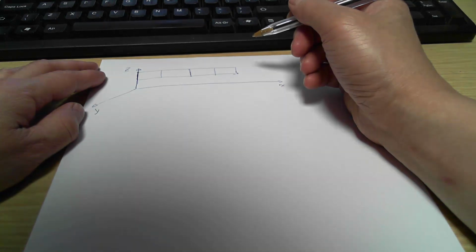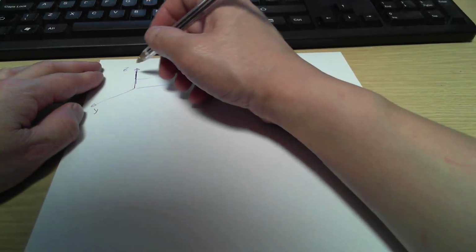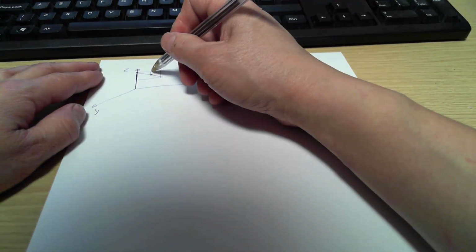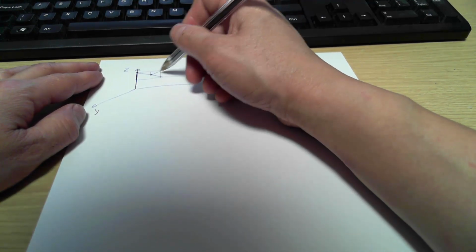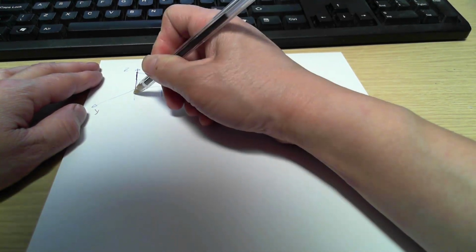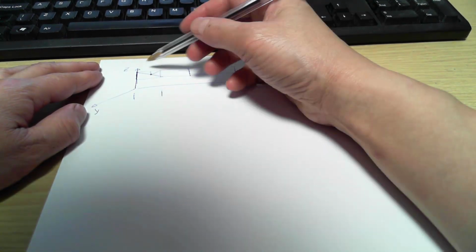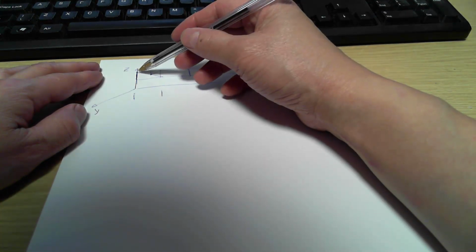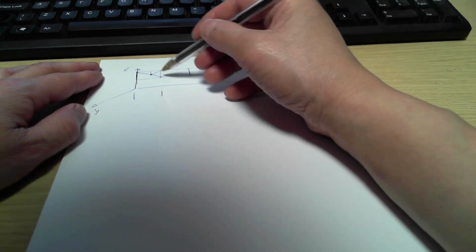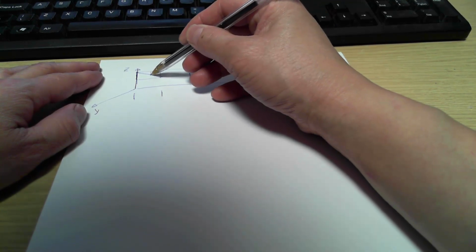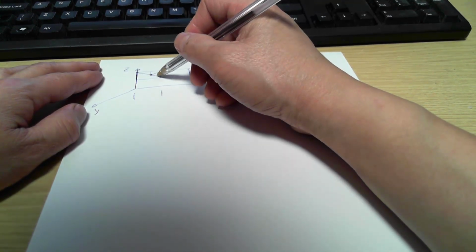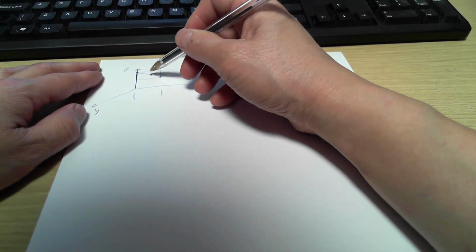If you look at the X direction, each bay of these structures is going to be divided into two small pieces, and then you connect in the middle, so you get that secondary truss member here. Each bay originally is 2.5 meters, but because of this, you need to divide this beam into segments. You need to draw from here to here, and here to here. You cannot draw from here to here, because if you draw that way, this beam is not actually connected with these two. To enable this connection, you have to separate the beams into two segments, so all the joints connect here.